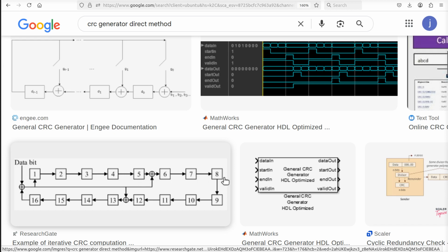The next digit in your hex, if you're going to give them a 16-bit polynomial in hex, this will be a 2, because it's between the 0 and 1 bits of this 4-bit hex nibble. Okay, this one down here, 1, 2, 3, 4, will be a 0. Okay, and then the most significant digit in the hex polynomial will be a 1. So as a hex constant, you'd have a 1, 0, 2, 1 for this polynomial here.